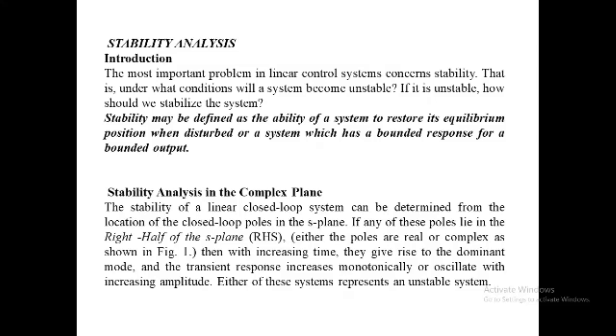For such a system, as soon as the power is turned on, the output may increase with time. If no saturation takes place in the system and no mechanical stop is provided, then the system may eventually be damaged and fail, since the response of a real physical system cannot increase indefinitely. See this diagram, a pole located in the RHS gives an unstable response.